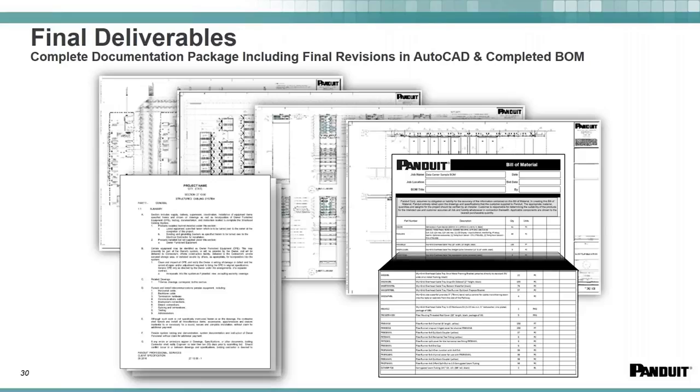The second chapter then is how you handle the materials, how you're going to receive the materials, what you're going to do when you're putting up the materials. It'll go down to the detail of saying, this is the spacing that we need to achieve to support the cable between the MDC and the IDF, identifying that we'll be using, for example, non-continuous cable supports like J-hooks, things like that, and the spacing requirements for all of those, as well as methods for maintaining the bend radius, how you're going to handle the fiber, and things like that. So all that's in the middle chapter.